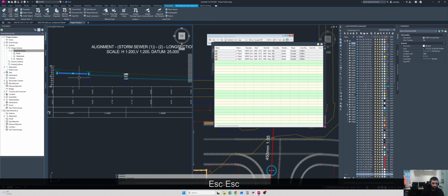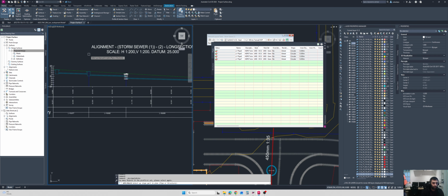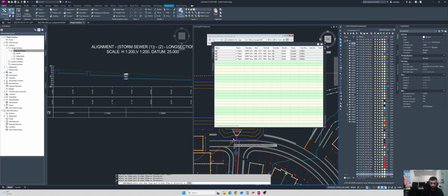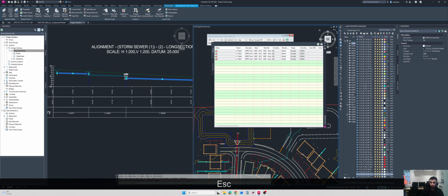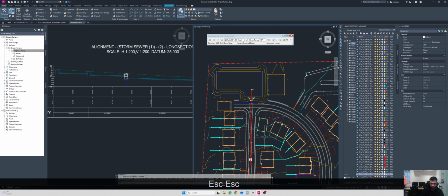For applying this one, select any two, go to modify, apply rules, and select the first one. Select upslope part in plan. Okay, so we have to select in the plan view, and then the pipe. Now let me just show you again so that you will have a better understanding.